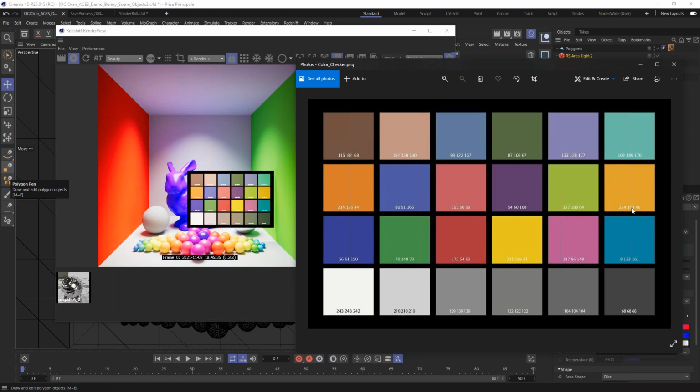And in the color remap tool, you can upload a sample color to your library if you're working with a brand that has a specific color, and then you can simply use the eyedropper tool to pick that color, and the color remap will remap that particular color to the color that you pick. It's just additional information, Lionel. Hope you don't mind. Yeah, exactly.